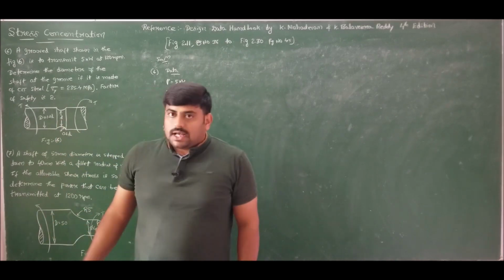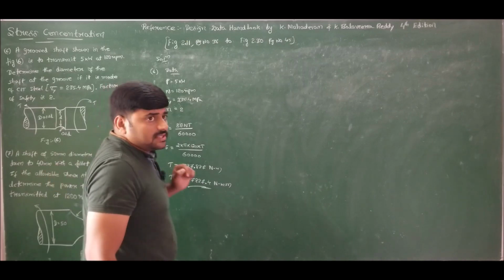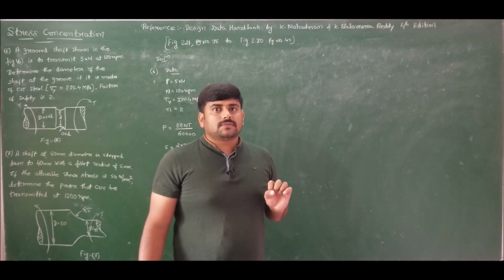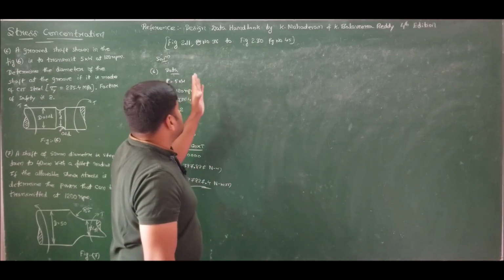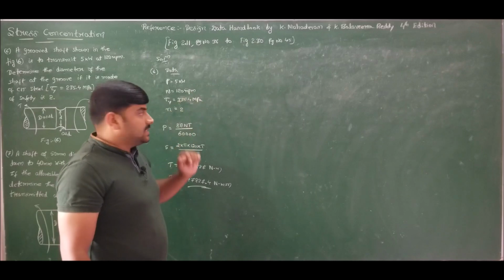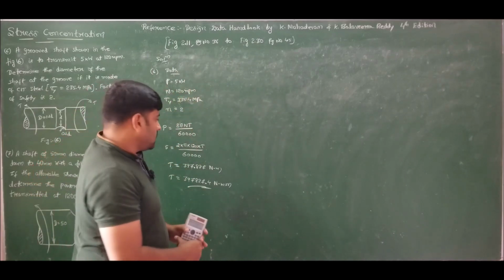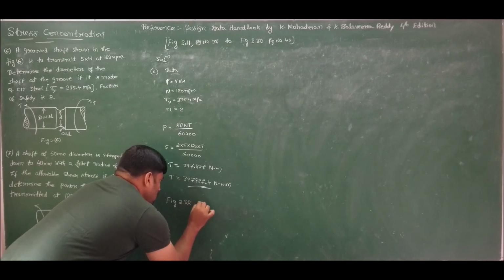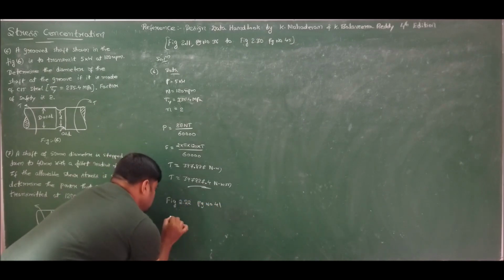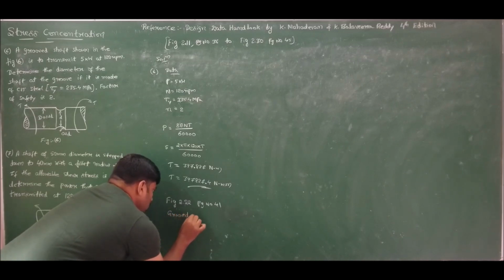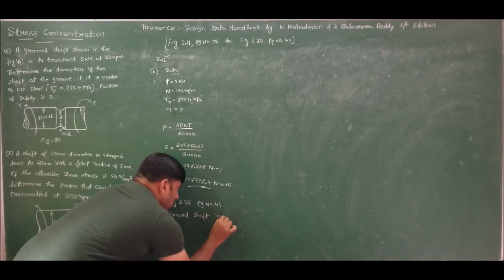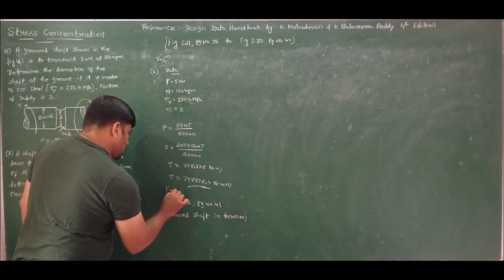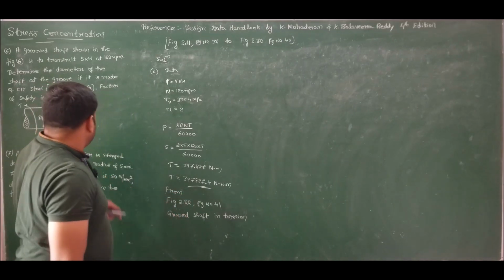As we all know, whenever there is a change in cross section or geometric dissimilarity, there are stress risers which contribute to accumulation of maximum stress, termed stress concentration, which can be solved by comparing the given sketch to the figures between 2.11 and 2.30. Comparing this sketch, I found that figure 2.22 of page number 41, grooved shaft in torsion, is similar to the given problem.